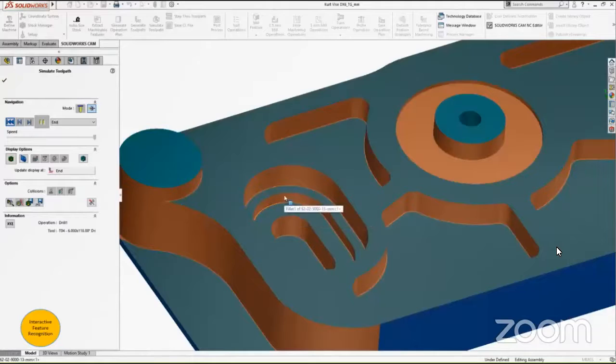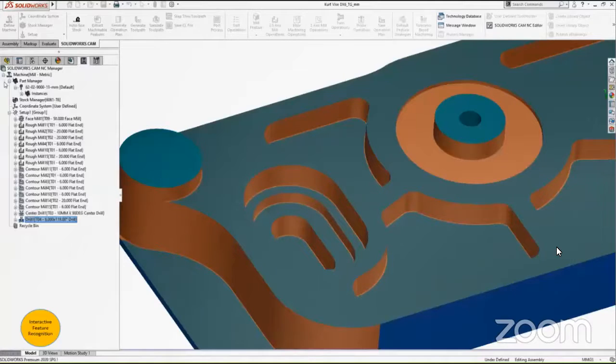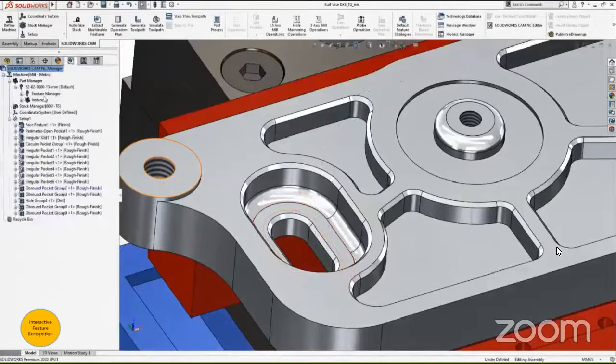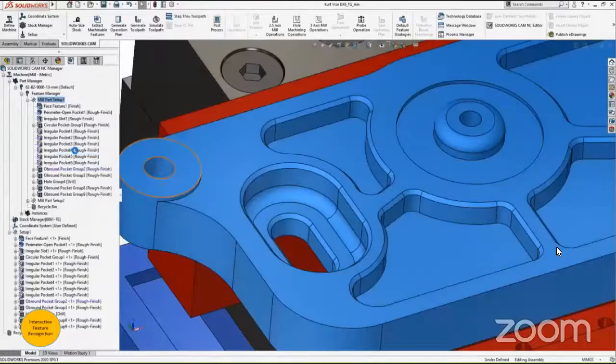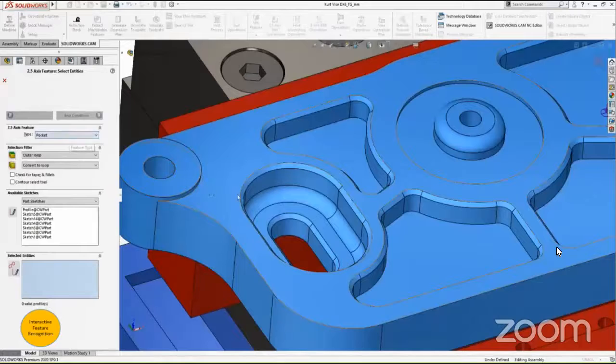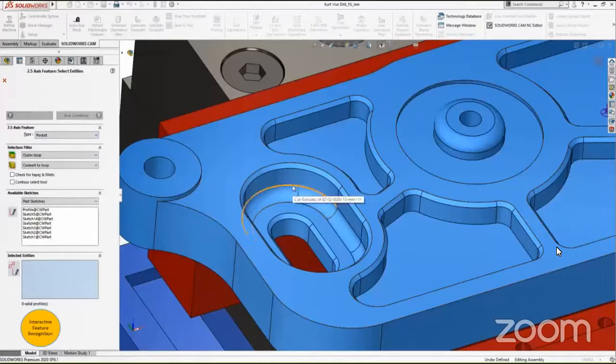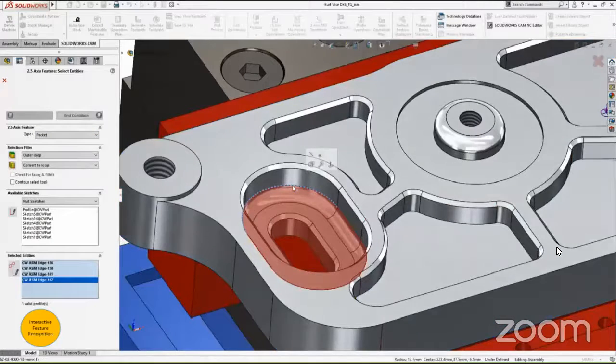So at the corner, we have some material left, and at this area, we have to use a different tool. So it will create the bottom round fillet as well. So for that type of machining, we require a ball nose type of tool. So let's create the feature. Again, go back to the feature tree, select the 2.5 axis and the outer edge that we have to create the fillet.